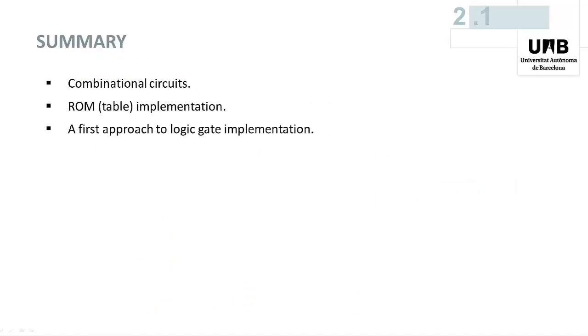What have we seen today? We have defined the concept of combinational circuit and have seen 2 kinds of implementation. The first one using a read-only memory, generally an inefficient method, and the second one using logic gates.